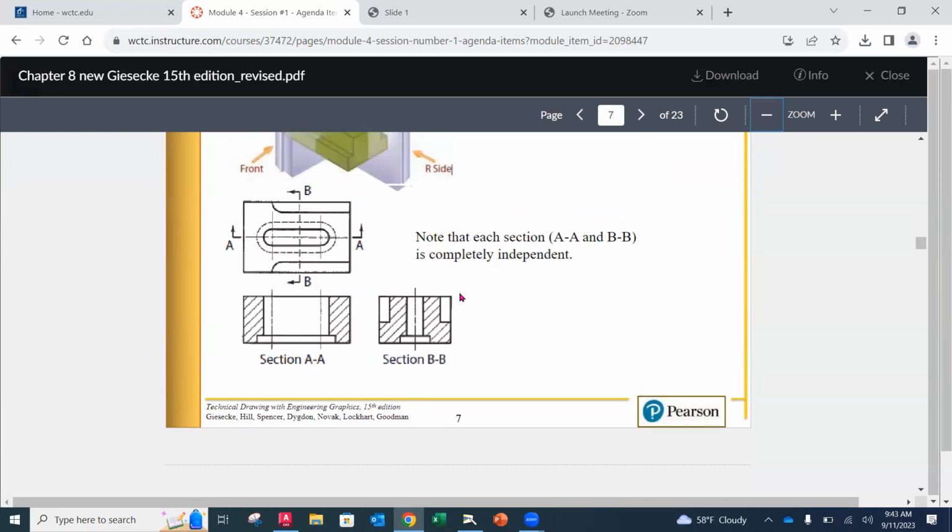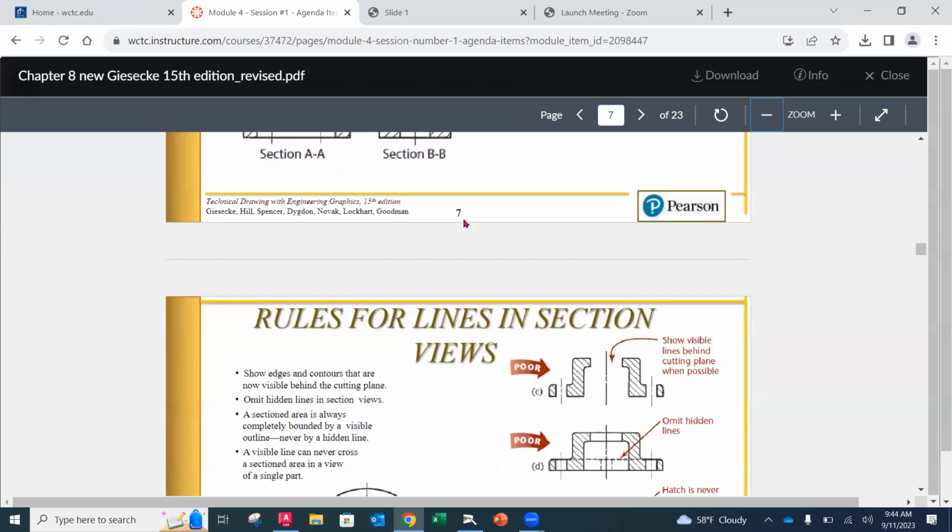But you could, I will say that. I probably would. I would probably tip this up on end and put it in projection like normally. Only if you don't have room to do that. And sometimes you don't. There might be a view there, and then you do have to place it somewhere else, but then you have to make sure that you label the view.